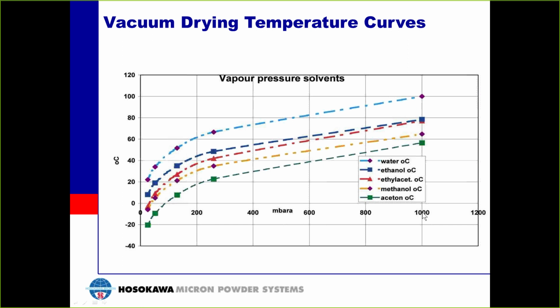As you reduce the pressure, you're reducing the temperature that the water will boil at. If you keep reducing the pressure, once you get down to about 250 or so millibars, at 65 degrees C, your water will boil. So say your product can only take a temperature of up to maybe 75 degrees C, then vacuum drying would be a good solution because you only need to heat up to 65 degrees C to evaporate off that water. So you can see how this can be advantageous.